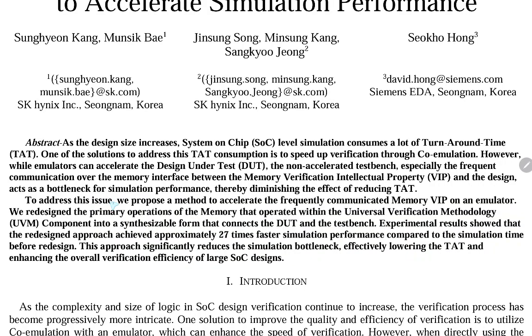To address this issue, we propose a method to accelerate the frequent communication with the memory VIP on the emulator. We redesign the primary operation of the memory that operates with the universal verification methodology (UVM) component into a synthesizable form connected to the DUT and test bench.